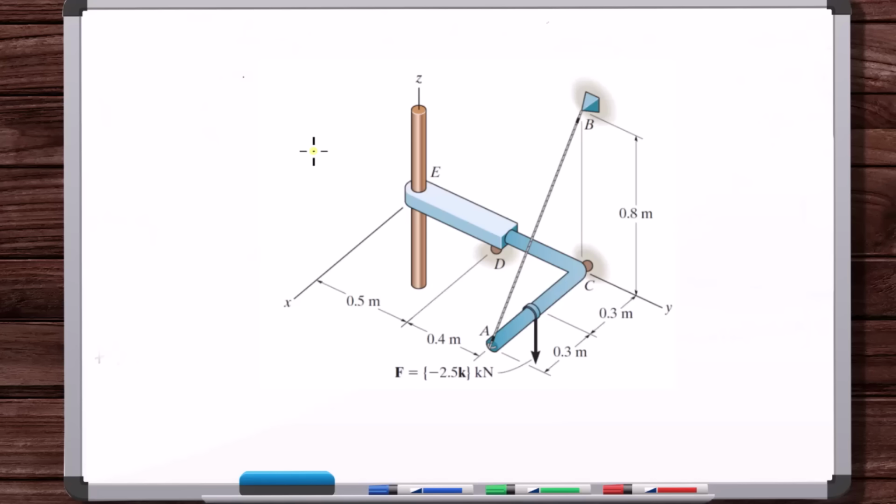Now, surface forces, if you have like a wind load or whatever, if it's in 3D, it's in 3D. It's a vector that's in 3D, or a distributed load in 3D. Now, for support forces, if you remove a bolted connection or any kind of support, it's the exact same idea as we did in 2D. You're just saying, what is this support? What kind of motion is it resisting?